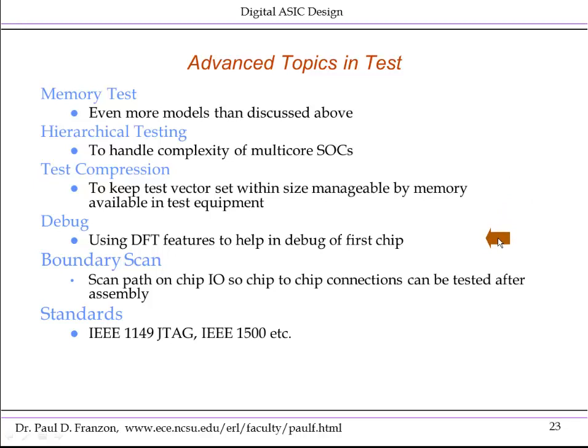We do not talk much about debug. These DFT features can be useful in debugging a chip. For example, using the scan registers to get the chip into a specific state that's then clocked for a few cycles in order to determine what's going wrong in the states after that. This is a very common practice. The design engineer is often involved in this. And sometimes there are additional features put in to support debug, but these are usually analog-like features like noise detectors.